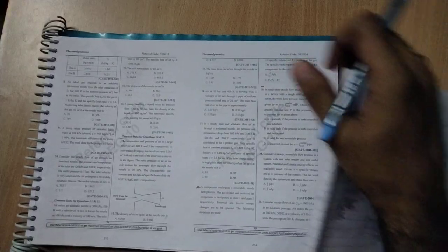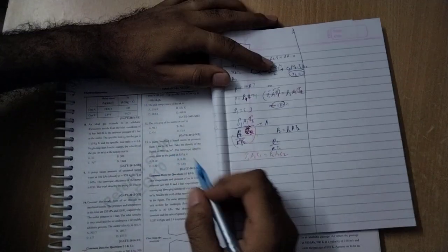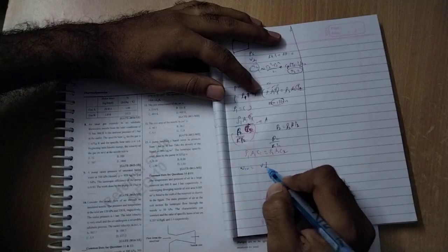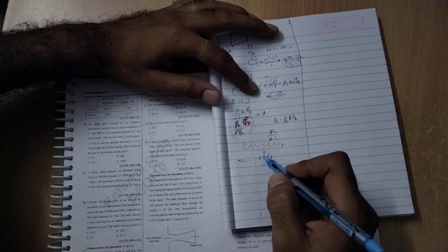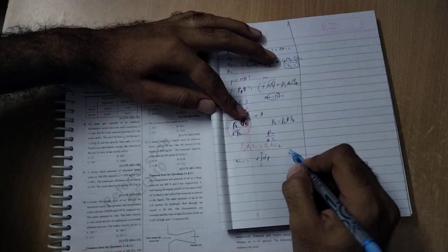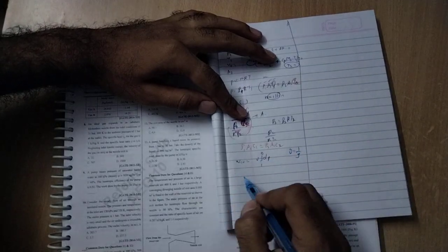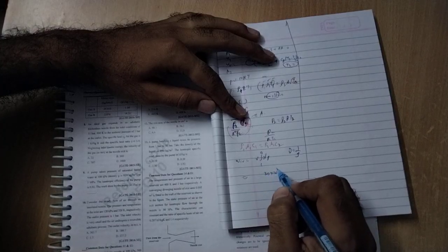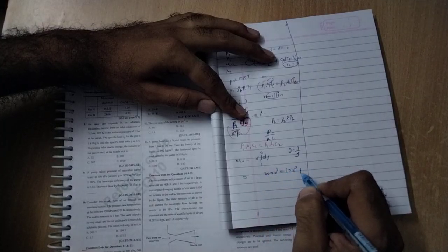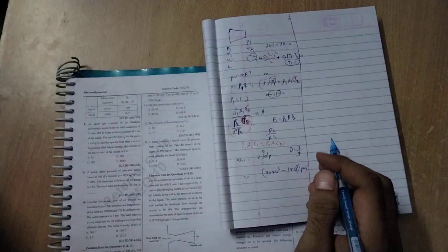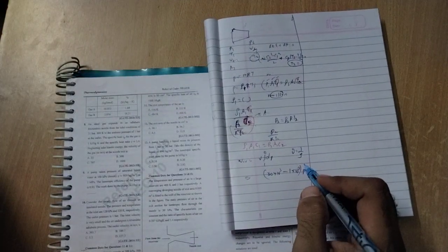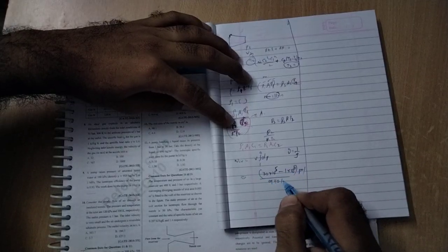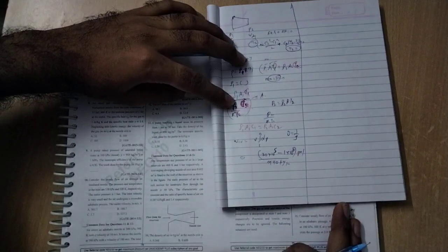So the pump is handling pressure, you can see this one. What is the work done of the control volume? It equals the integral of v dp, from inlet to outlet. Since they have given density, the specific volume equals 1 by density. So 30 bar, 30 into 10 power 5 minus 1 into 10 power 5 Pascal, since it is given in bar, divided by 990 kg per meter cube. So just put it in and we can calculate the answer.